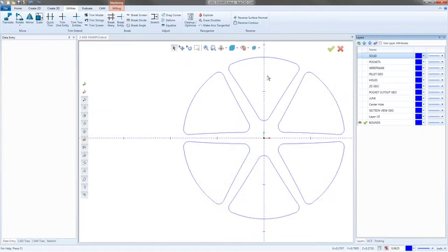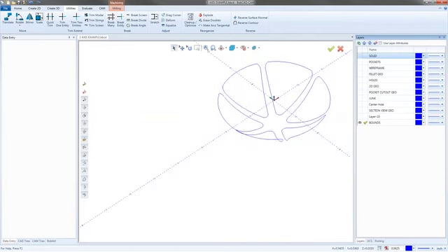The best way I explain it is if you took your end mill and put your eyeball on the tip of that end mill and looked straight down through your boundary, you should always see the geometry that you're trying to cut. Doesn't matter if the boundary is 150 inches above the part. It can be curved, can be 2D, does not matter. It could be a wireframe. You can even pick edges. So there's a lot of different ways to get boundaries here.